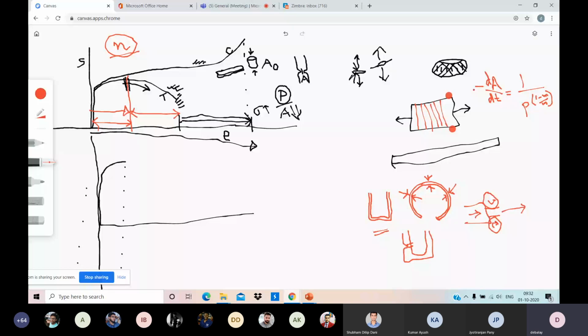That expression tells, if by chance any location's cross section is decreased, then the rate of decrease will be more compared to the other region. The decrease in cross section at other regions will be less, and if somewhere the cross section is decreased, there it will decrease at an even higher rate, which will continuously increase as the neck grows.